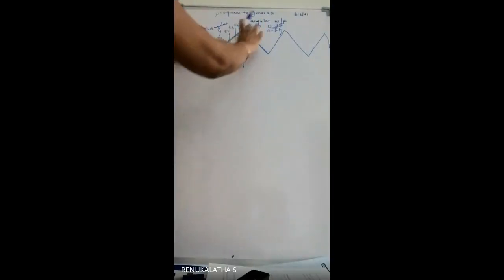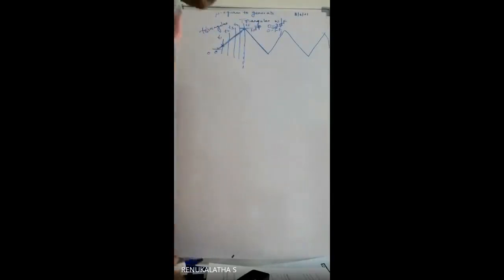Right. So in between 0 to FF, do you see a single value? Do you see a single amplitude or single magnitude between 0 to FF? No, ma'am. From the waveform it is very clear that gradually the amplitude is changing at every interval of time. Here at interval T0 it was 0, amplitude is 0. When you draw vertical lines at every point, you see that at every interval of time the value keeps on increasing towards FF, and when it reaches the maximum, FF or 255.